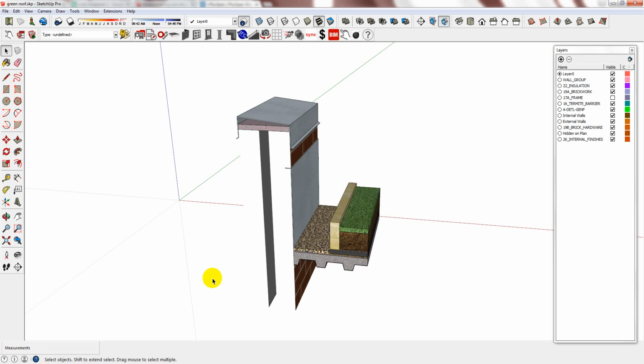In summary, to expedite your learning curve in Plusspec for SketchUp, spend the time to understand the different ways that you can control your Plusspec model. Layers and scenes are integral to creating an effective workflow and for outputting presentation and 2D documentation. Never work off axes. If you need to, create different types of files and save them separately. So for example, a master file, a sun study file, and a detail file or detail files.